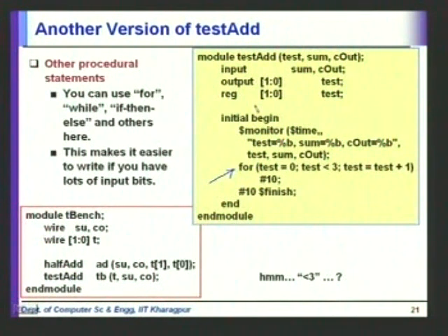It's an error first of all, because if you have a 2-bit register, then it cannot take a value which is greater than 3. Right. So if you try to assign it some value which is greater than 3 by test equal to test plus 1, then that is something which is an error. Right. Now, in what way will that error manifest itself?